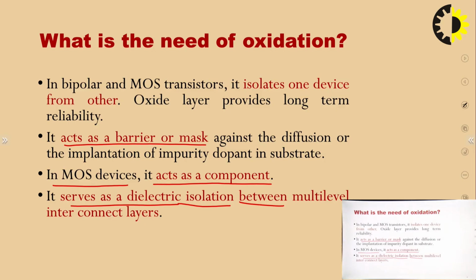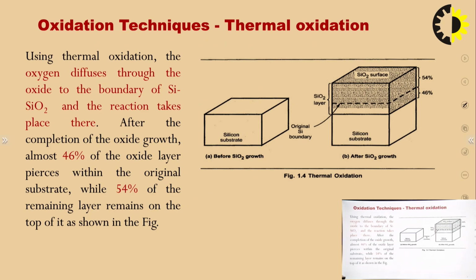As we know that in case of VLSI ICs that we develop, either we have a large surface area over which we can do the interconnection, but the drawback of that is the size of the chip gets increased. So, what we do is multi-layer interconnection, where the different interconnecting layers are isolated from each other by creating a layer of SiO2 between them.